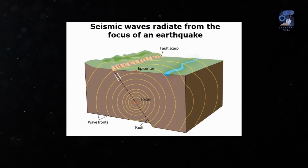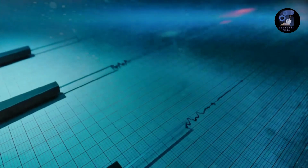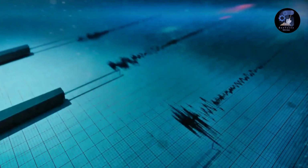During an earthquake, the waves produced are capable of shaking the dam in every possible direction. The effect of an earthquake is equivalent to imparting an acceleration to the foundation of the dam in the direction in which the wave is traveling at the moment. The earthquake waves induce forces in both horizontal and vertical directions.